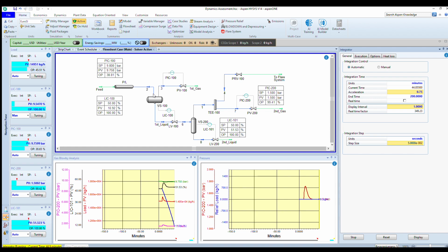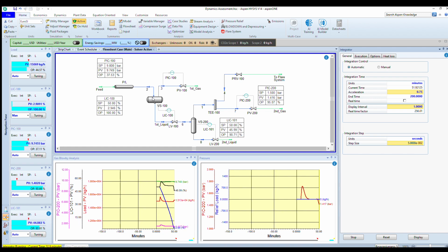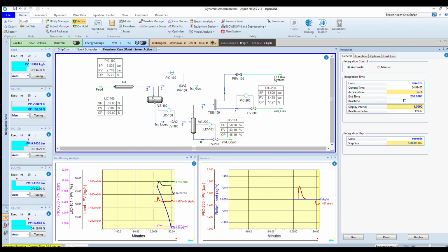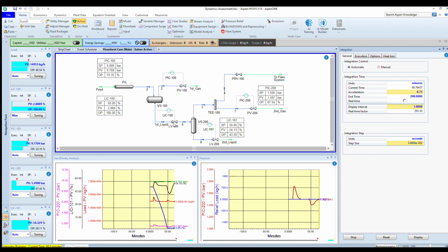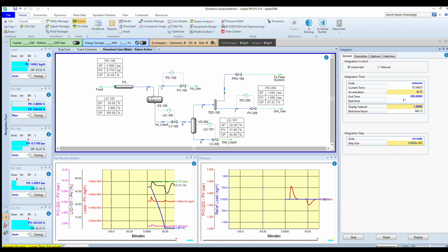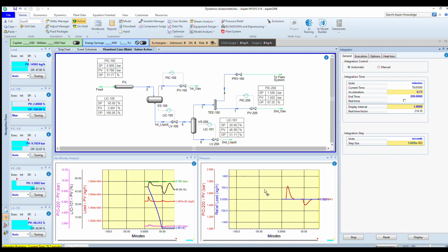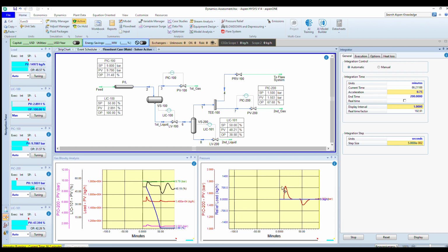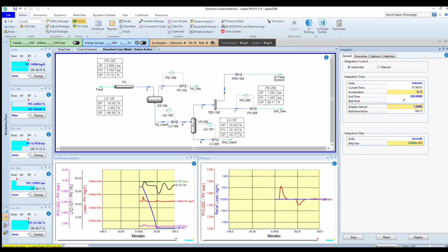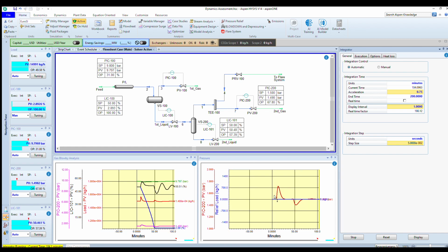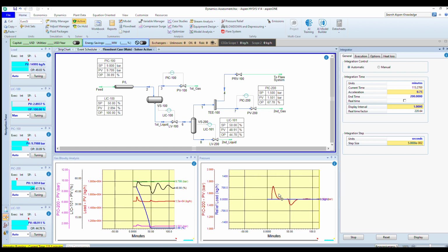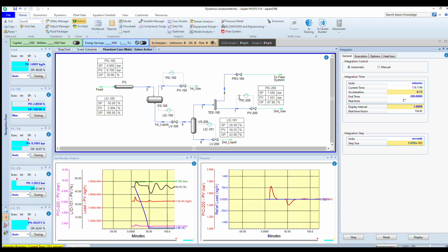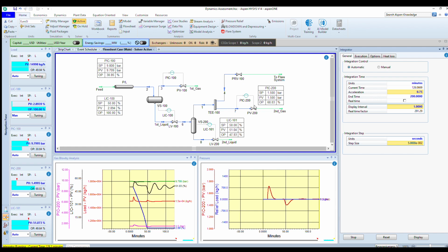Liquid here is actually decreasing, and it makes sense. This valve has significantly increased, and the entire liquid from HP to LP interface will migrate. As I can see here, the transient pressure fluctuation in the LP interface is going up and down. That was a slight increase, but very quickly it has been damped down because of the gas control system.